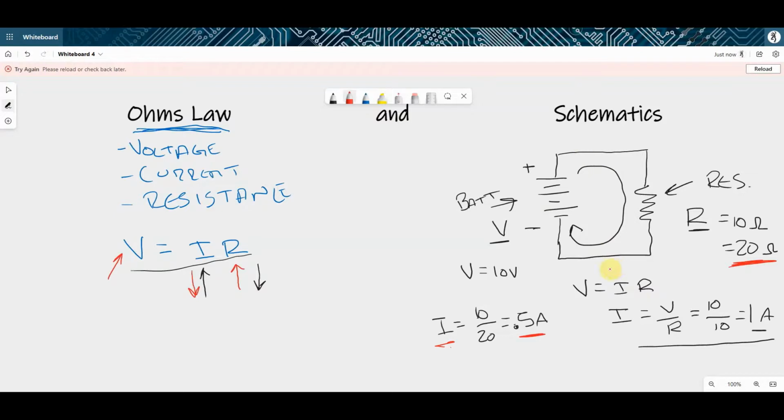You have other things in here, like a light, an LED, which is going to be our next lesson. And we have to limit the current that goes through, say, that LED. So we have to adjust our R to make sure we have the proper current going through that component. Again, all of that falls on the designer, which is us.